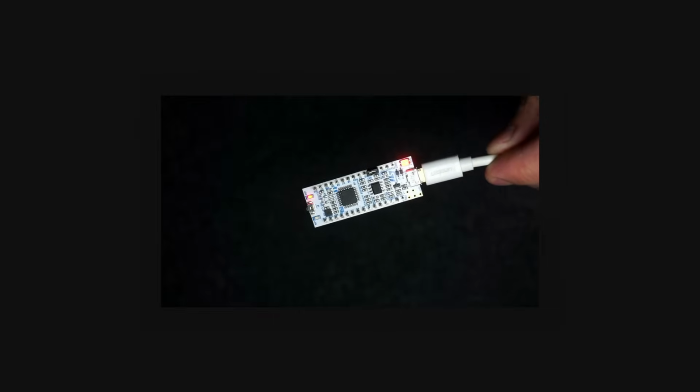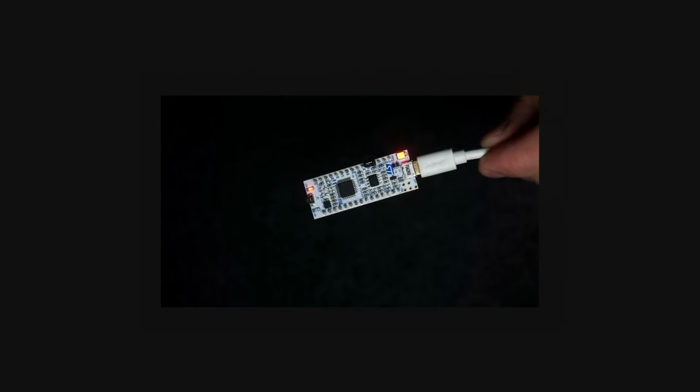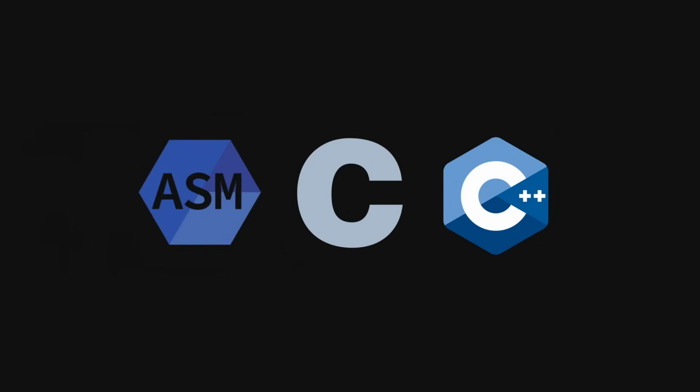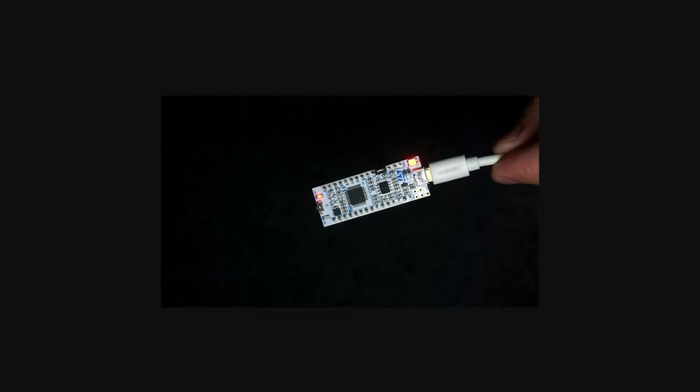In this video we are focused on a specific microcontroller, and I want to emphasize again that startup code will vary depending on the microcontroller hardware, the toolchain, and the other software components involved. The programming language also matters. We focused on C because it's the most common, but a language like C++, for example, would require more startup code, while something like pure assembly would probably need less. Either way, understanding the example in this video will make it easier to grasp others.